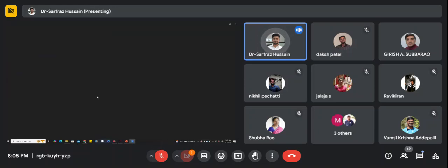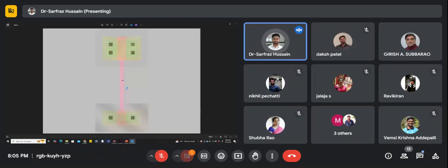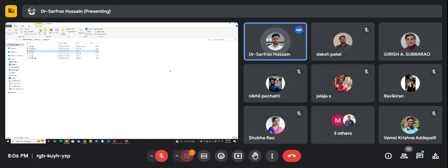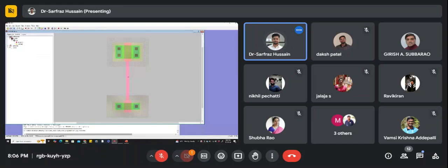This inverter.png file is nothing but your layout file. So you can see the layout. Okay, so you can either take a screenshot of the layout file or you can directly generate it like this. And if you want a white background, there are options where you can change the background image. Those things you can change using the preferences command. And finally, you can just save this particular layout or schematic. You can directly export it into a PNG file format.